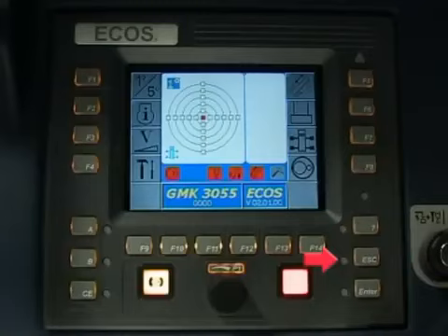The Escape button with LED provides navigation from submenus back to the main menu. The Enter button with LED provides input confirmation of selected values. This warning lamp indicates the status of the hoist limit switch. The lamp is on if the hoist is shut down by the hoist limit switch. The lamp flashes when the hoist limit switch has been triggered but shutdown has been bypassed.